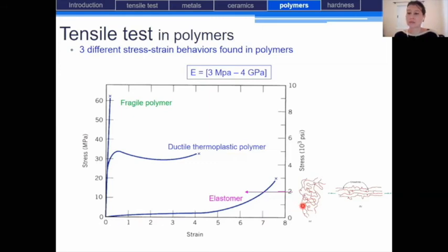And so when a tensile load is applied to this material, we will observe the alignment of the chains that have a high mobility in these conditions, and so they will align in the same direction as the load is applied, up to a certain point where the chains will be almost totally stretched, and so the crosslinking points will limit higher deformation.